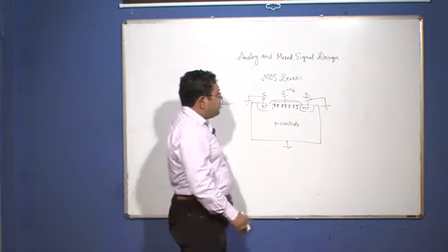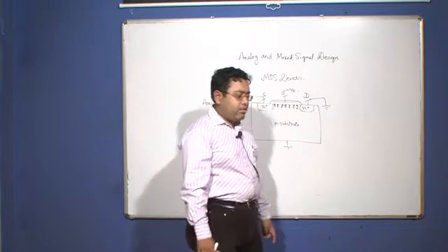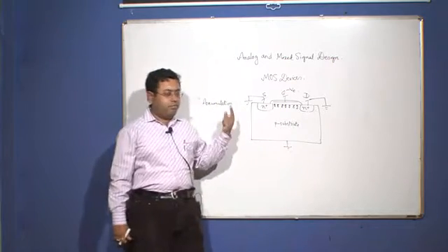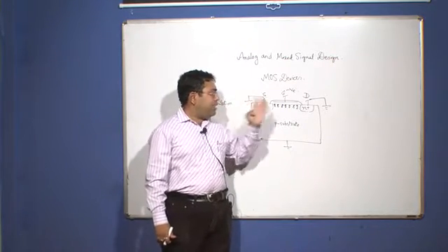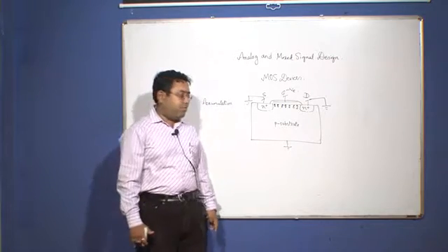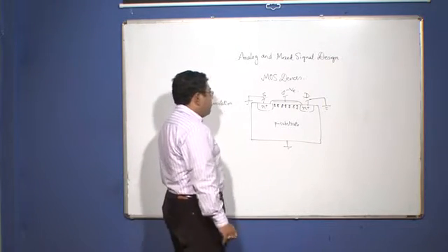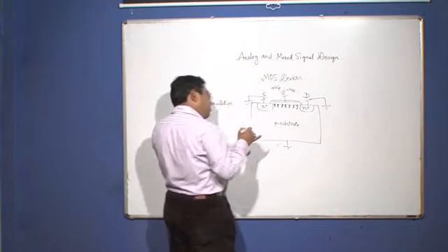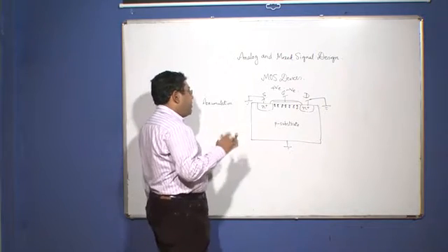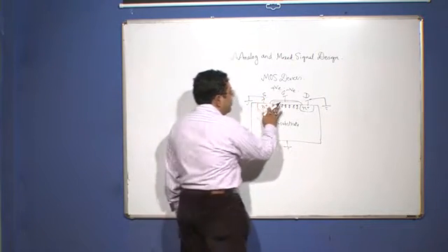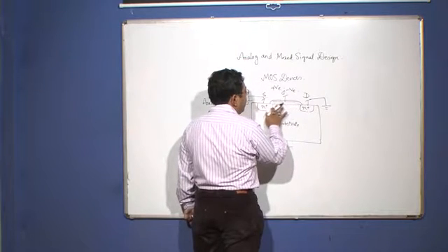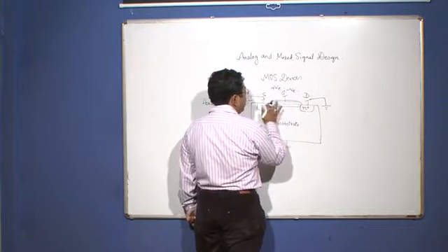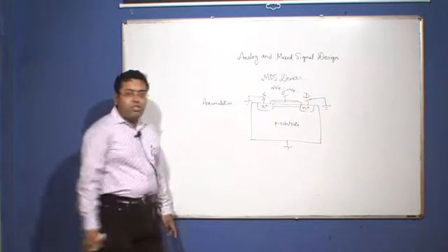Now, as you reduce the negative potential, you will see lesser and lesser concentration of holes, and at a particular voltage known as the flat band voltage, you will see that the entire layer of holes is wiped off. Now, if you apply a positive potential, it will repel the holes away from the interfacial layer between the oxide and the substrate, and a depletion region is formed at the interfacial layer between the oxide and the substrate.